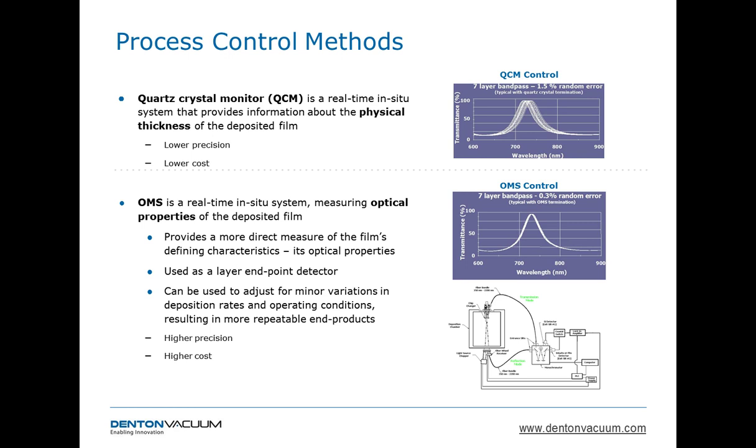But in addition, since quartz crystal monitor also can be used as an endpoint detector, OMS can also provide and adjust for minor variations in the deposition rates and the operating conditions of the system, resulting in more repeatable end products.